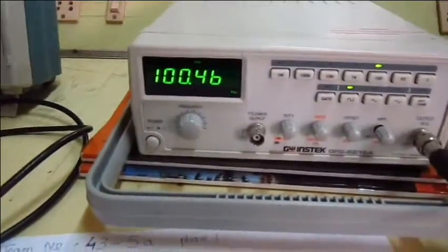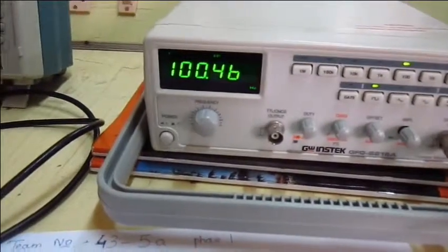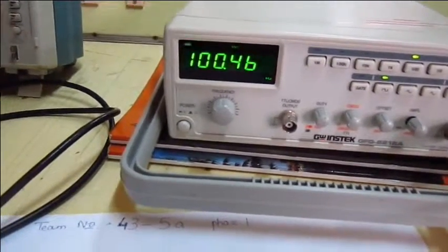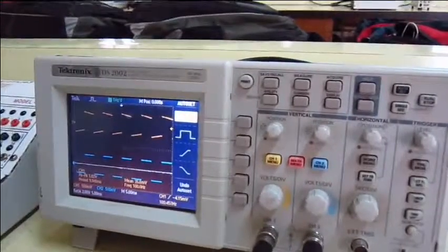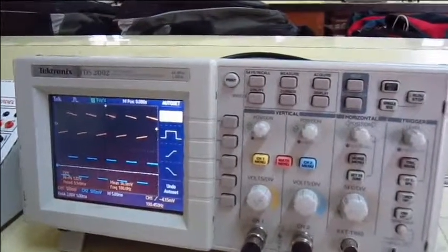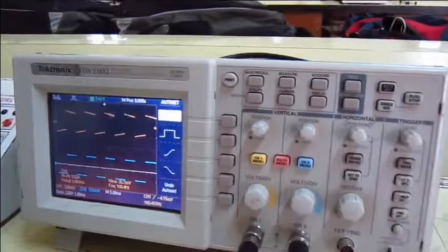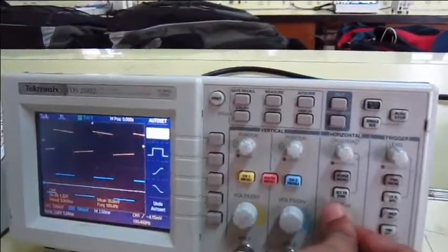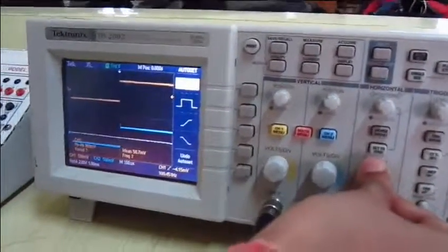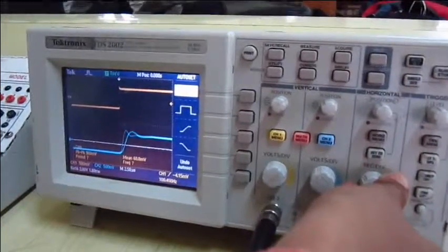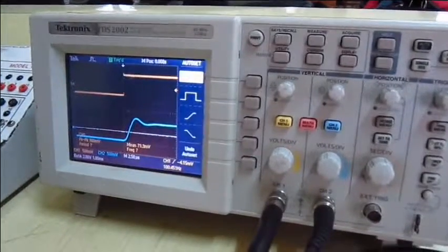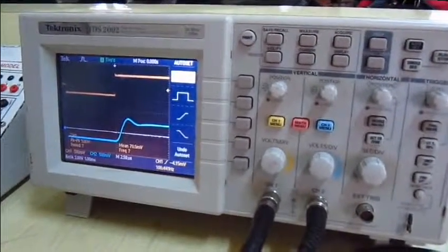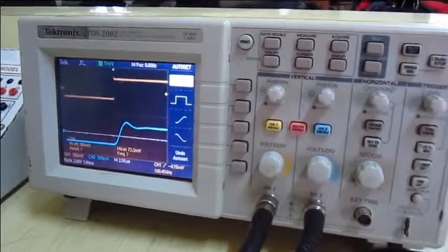This is part B of our problem, and as you can see, we have applied a 100 Hz square wave signal. The output can be seen on the oscilloscope screen, and the output voltage is following the input voltage. However, if you look closely, where the input voltage change is sharp, the output voltage does not follow exactly, and there is a slight distortion.